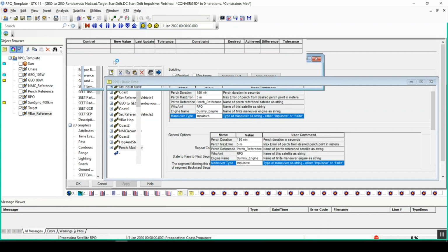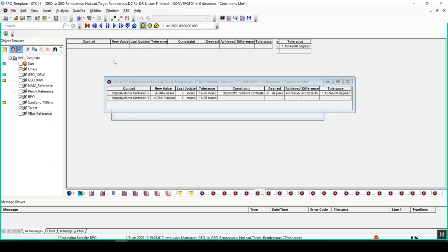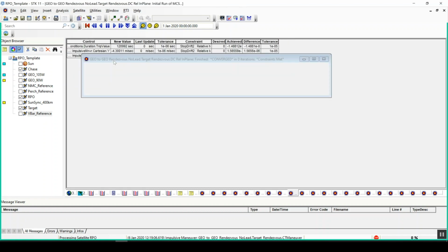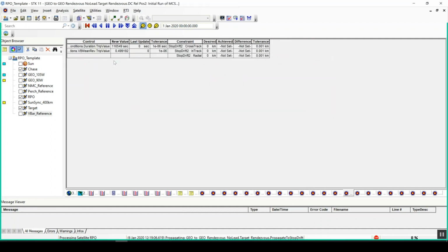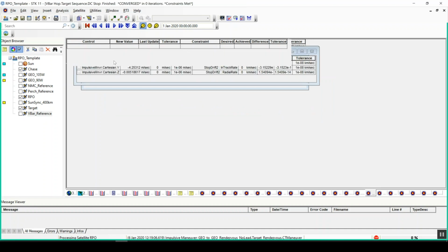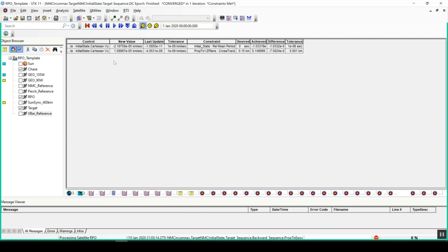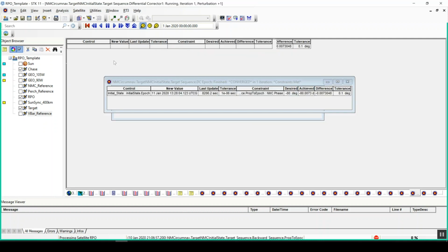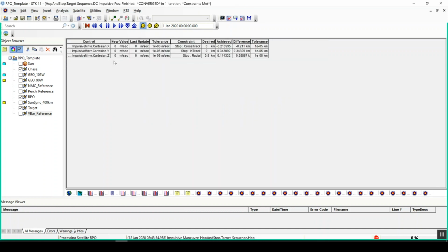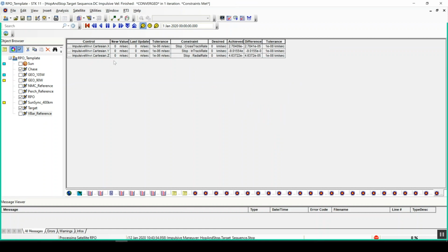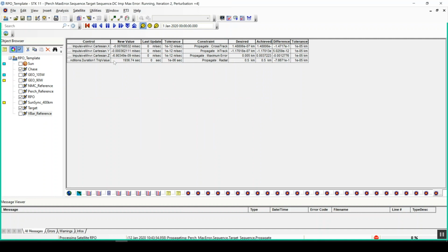So now we've added a hop to an inspection point, and then we wish to persist at that inspection point and hold that position for 3 hours, and this will compute all the maneuvers required to hold it for 3 hours. As you know, anytime you're on the radial direction above the target, and with 0 relative velocity, if you do not perform these maneuvers, it will tend to go up and to the west, away from the target initially. And it will leave the scene naturally and safely.